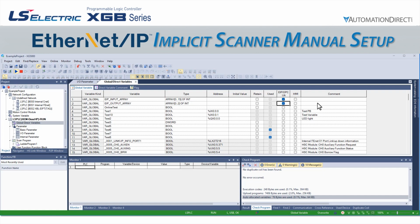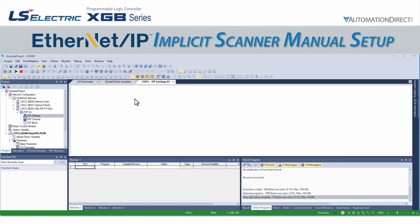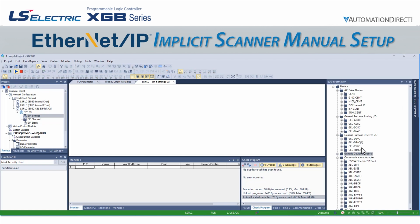We will now add a generic EDS file to the project. If we maximize our EIPT card and then the P2P03 connection we created in the video on configuring the EIPT module, we can double-click on EIP Settings to open the LSPLC EIP Settings 03 tab. Here we can drag and drop the generic EDS file that comes included with the XG5000 software.